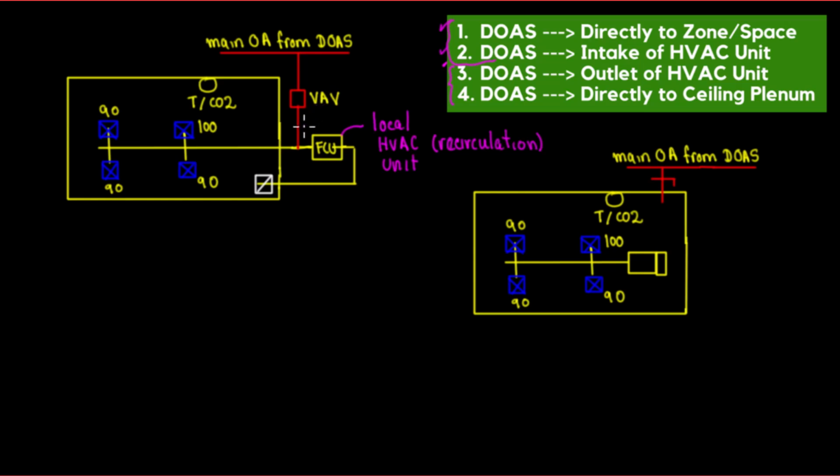And as everyone remembers, in the VAV box, actually, the requirement for this space, I'm going to put this in yellow. So this is the conference room, right? So I'm going to put again in here conference room. The requirement for the conference room was an outside air of 75 CFM, right? 75 CFM. So technically we're inputting 75 CFM in here, and this is going to get mixed by the FCU.